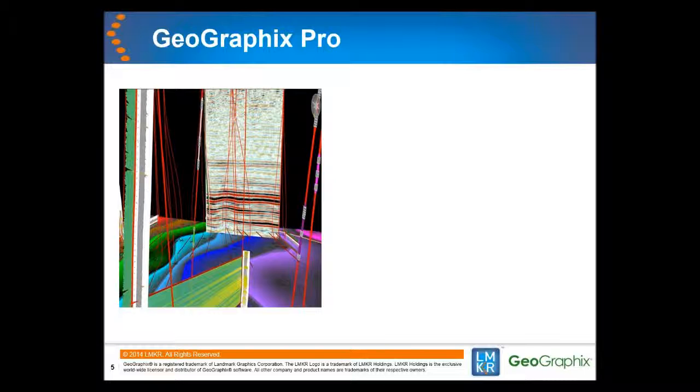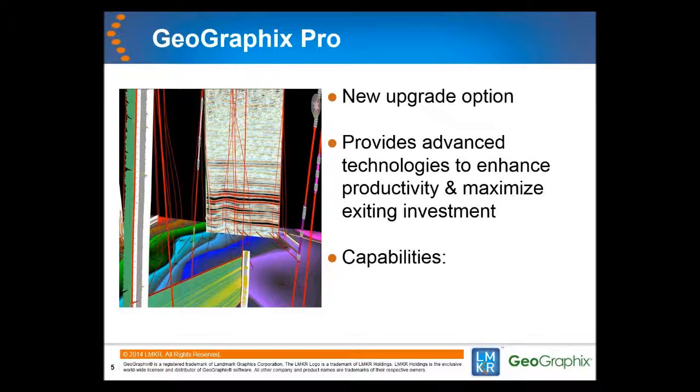In this webinar, you will be introduced to the new Pro features in Release 2014.1 and the new LMKR Well Planning utility. The Geographics Pro package consists of two new features for 2014.1. The Pro Field Planning, which allows engineers and geologists to quickly create multi-well field plans, and Pro 3D, which allows the users to graphically select a region on a GeoAtlas map and automatically load all the 3D objects on the map, like wells, cross-sections, isomaps, into the scene.